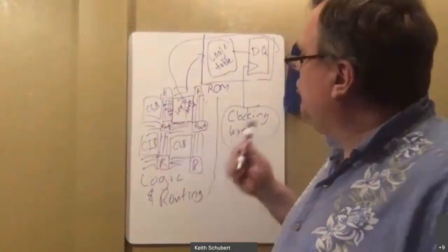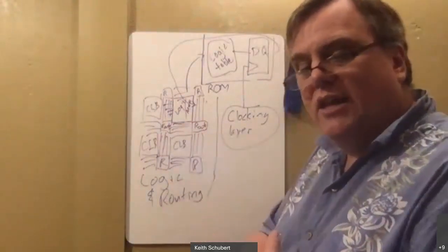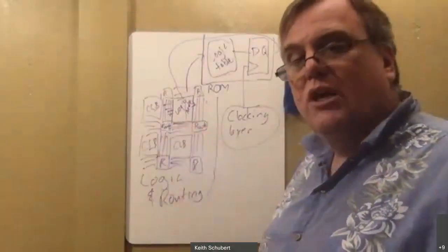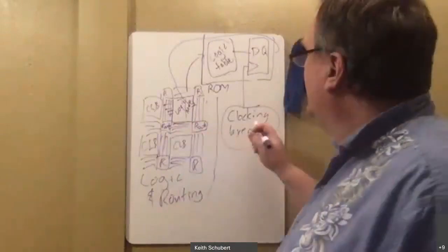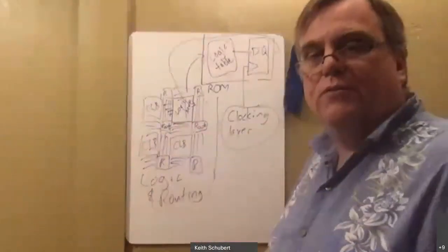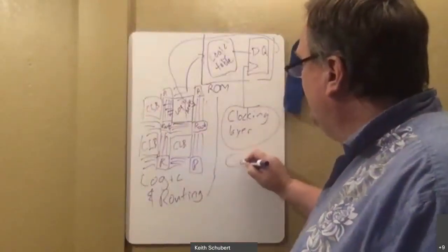So if you attempt to build an FPGA design that goes into a clock from one of its logic signals, now you can mention different clocks. There are ways to get different clocks. This clocking layer can have like 16 different clocks, and you can set them differently and stuff like that. But this has to be set in the constraints file.